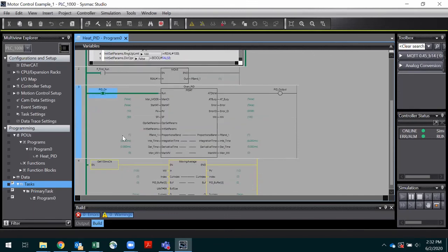There are 3 tuning variables there: the proportional band, the integration time, and the derivative time. Give them 1 second on the 2 time ones. Yeah, so just 1 second, and then 1 second on that. Now you can flip the start AT bit.